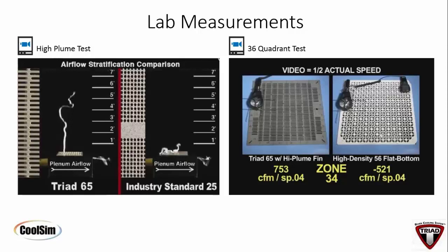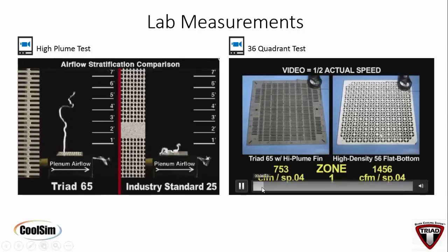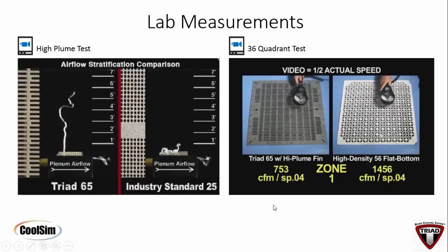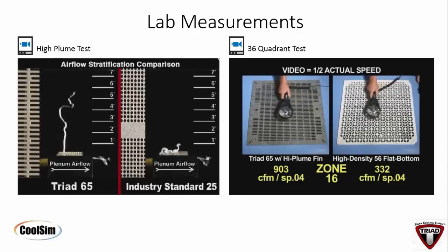If you'll rerun that again, Paul, at the very top corner, it's actually flowing a lot of air, a very high CFM. What we started to see here, again with the Triad Ice compared to this 56%, is that it goes from very high and drops down to 332 CFM. It's fairly consistent in the center of the Triad, and that was part of the design we were after.